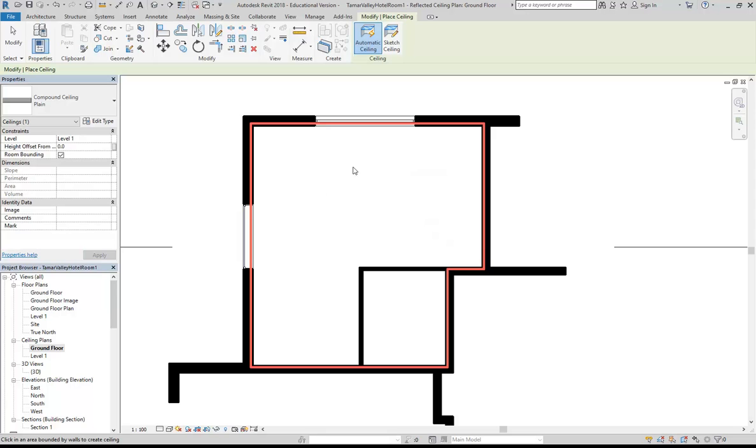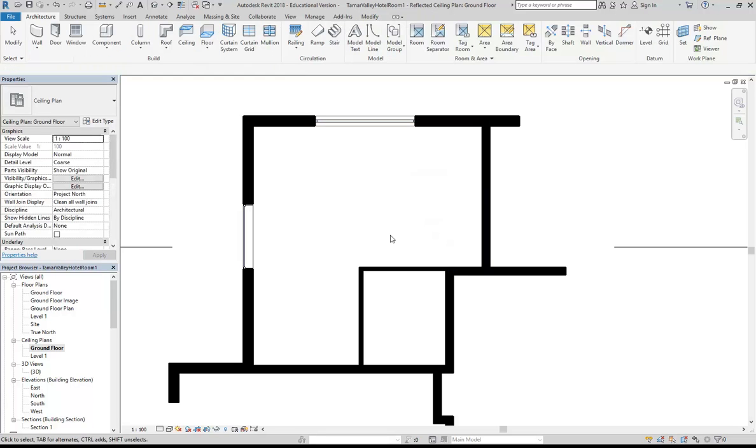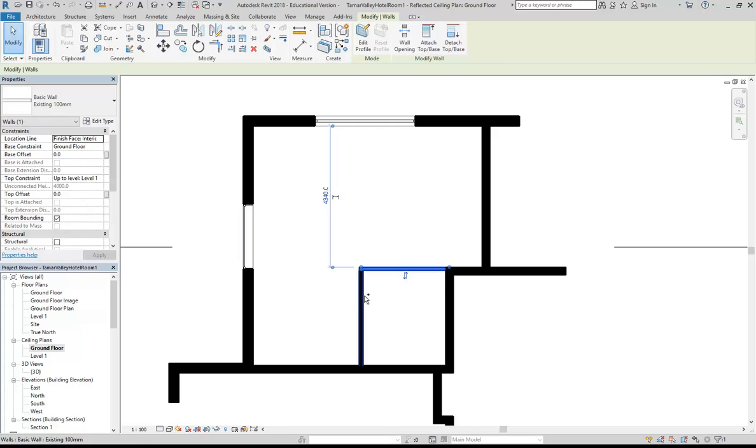And so actually, sorry, I've missed a step because it's missing the internal wall. So I might just select those and bring them up. Yeah, I've got to think about this one. Definitely want to do a drop ceiling. So actually, I'll just make those 500 as well. So I should have probably just done all the walls 500 up, but maybe to make it different, I'll make this one 200. That will become clearer later.